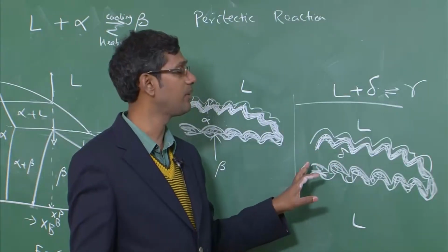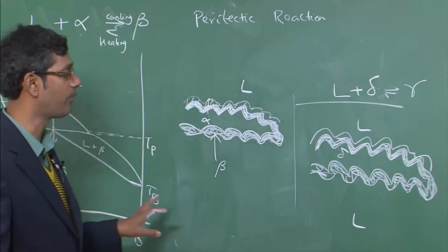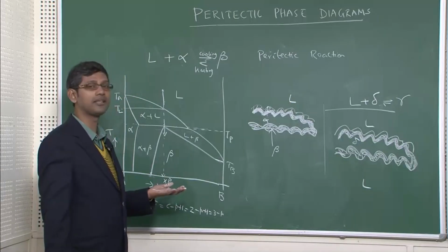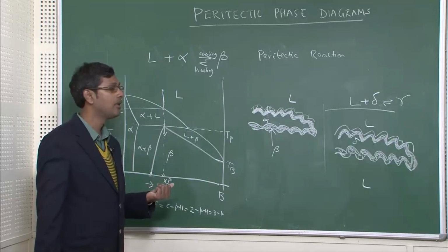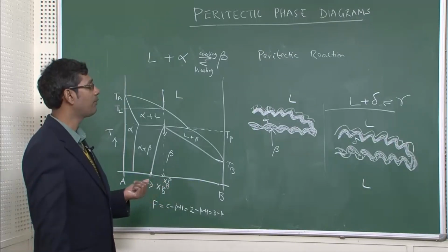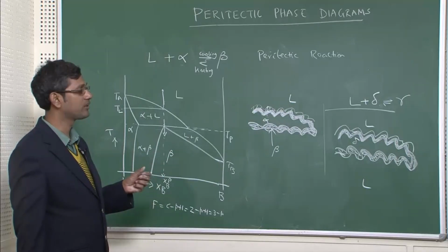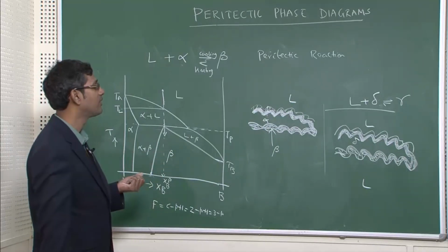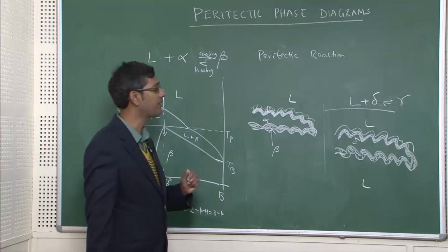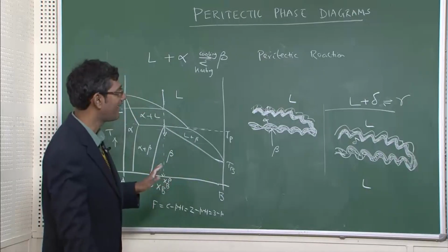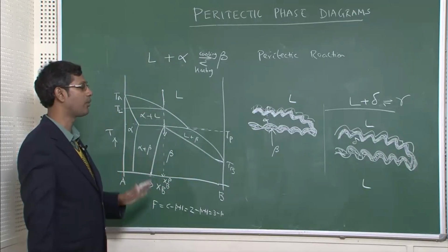In all stainless steel you can have this problem, and in fact stainless steels contain iron, chromium and nickel other than carbon. So there chromium can segregate and react with carbon and form chromium carbides. There is another additional problem which we will discuss later, but from the perspective of the peritectic reaction you understand that this can create problems.